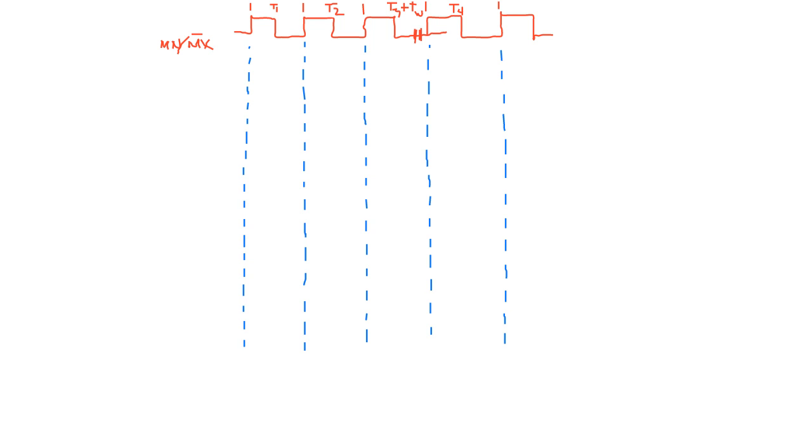Okay, so if it is like MOV AL, [2030], that means it is a memory read operation, right? First of all, this read and write control signal, it must be high for minimum mode throughout the time. Okay, fine. And then what are the control signals we need?